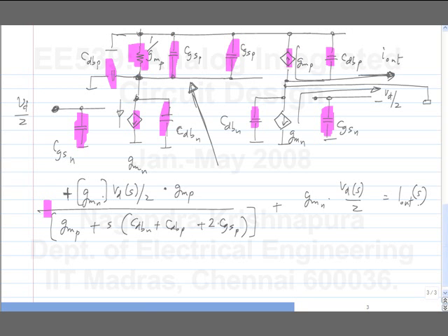So one part of the current goes through some frequency response which has a low pass response. Okay. So this path has a low pass response. Obviously, at a frequency where these capacitances dominate, this node voltage becomes almost 0. Okay. At very low frequencies you will have the current through this GM mirrored by the upper current mirror, and driven to the output.